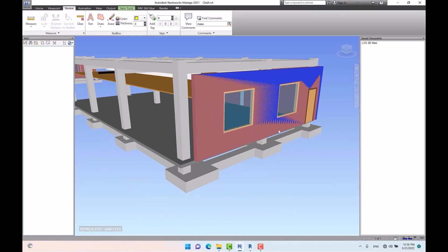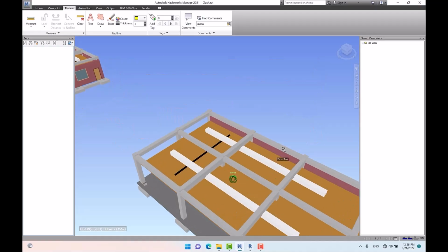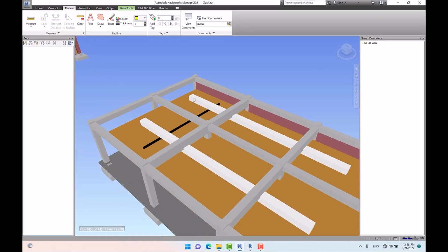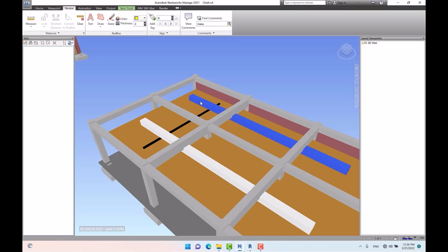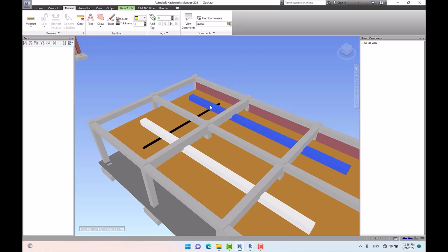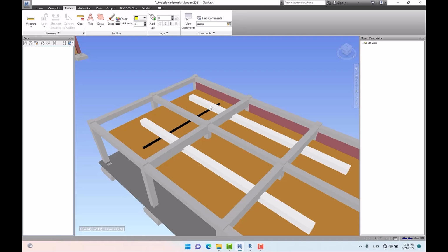For example, check this out. Here if I select this wall, as you can see the conflict or clash is clear. If I select the duct, if I select them or hide them, as you can see we got duplicated ducts here, which shows the conflict. Undo, again I select it, then I hide it. Look here, select hide.